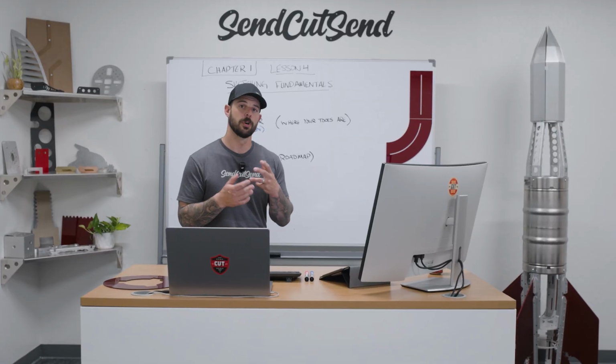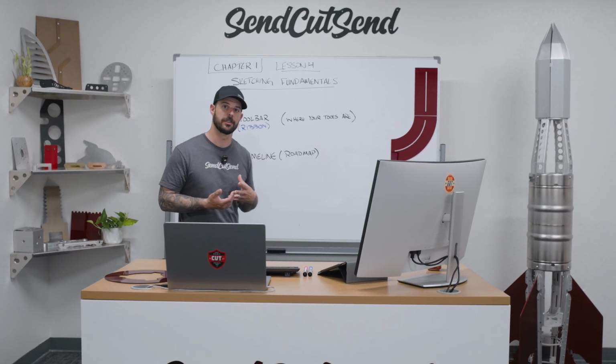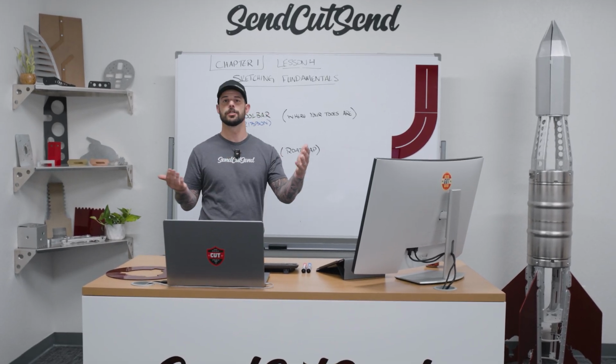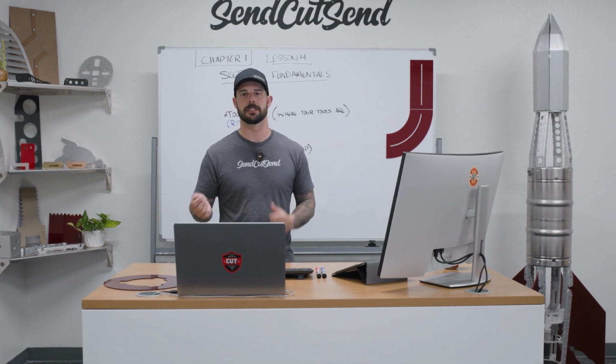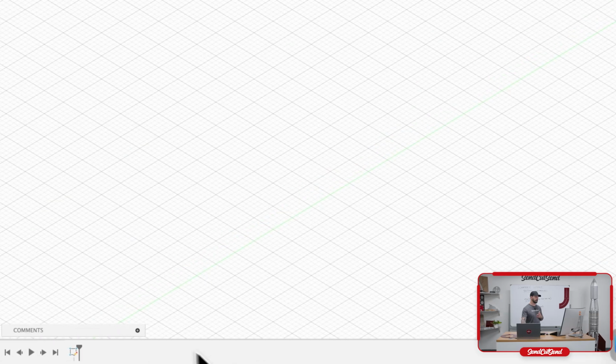Now, one of the most important things that the timeline or roadmap does for you is that it is a history of what you've done so far to create that part or model that's in here. This allows you to rewind all the way back to the beginning before you created a single sketch, or midway through your process, or all the way back to the end. And you do that through a couple different methods.